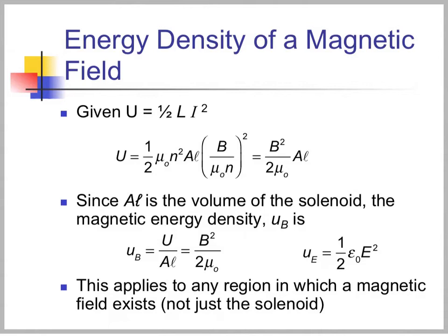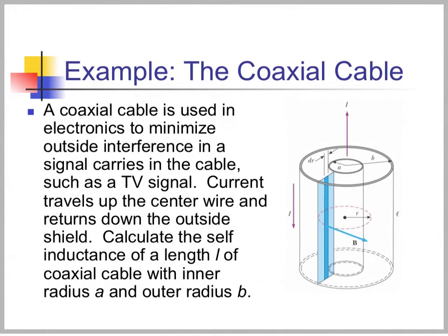So let's look at an example problem, a coaxial cable. They're used in electronics to minimize outside interference in signal carriers, such as a television or a cable signal. So first, what is the magnetic field in between? We know that the magnetic field in between is mu naught I enclosed over 2 pi r. I don't care about the field inside the wire, or out here. I only care about what's going on in this region, and we can use Ampere's law to figure out exactly what it is. Long straight wire. Current travels up the center wire and returns down the...